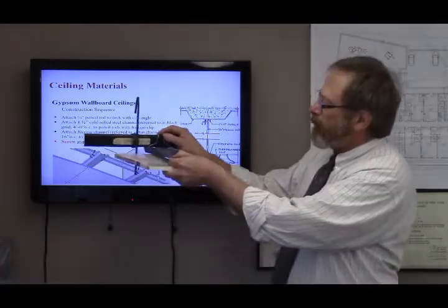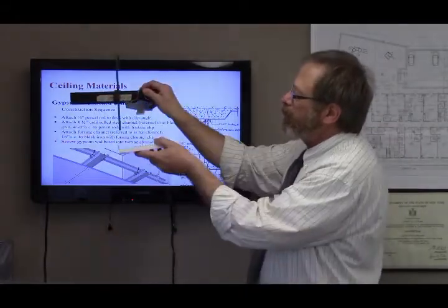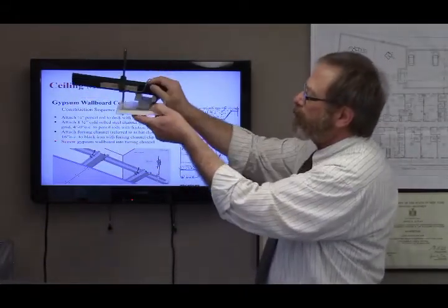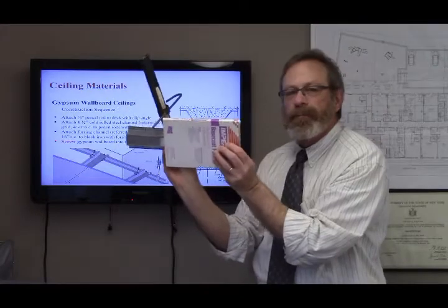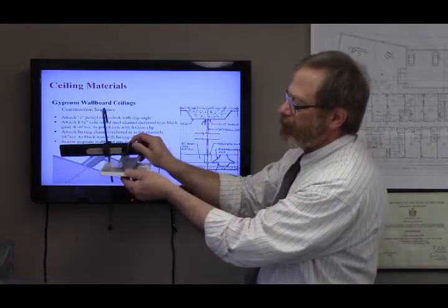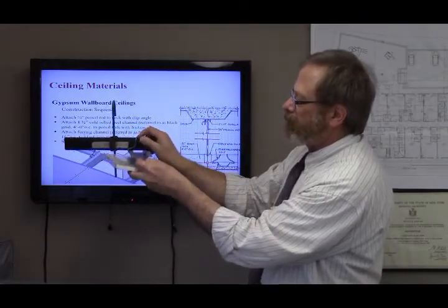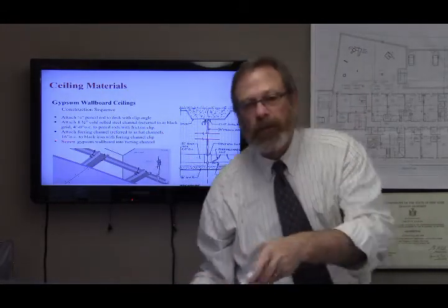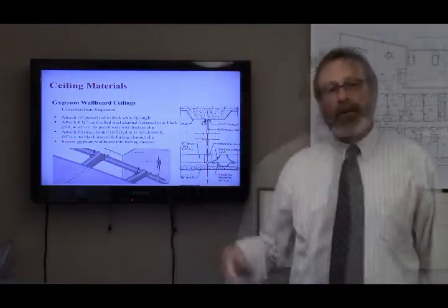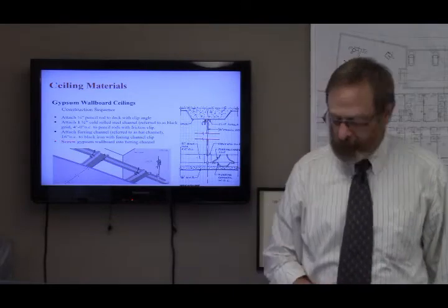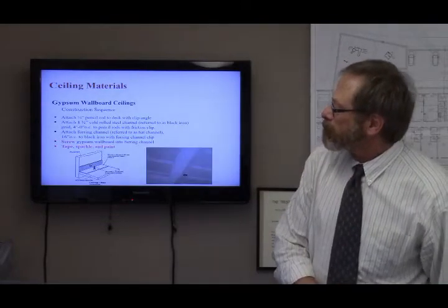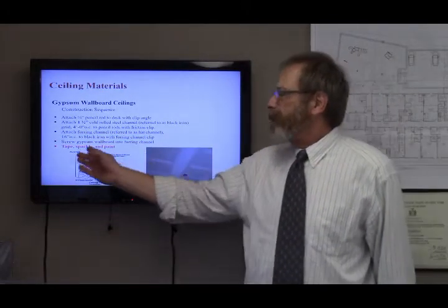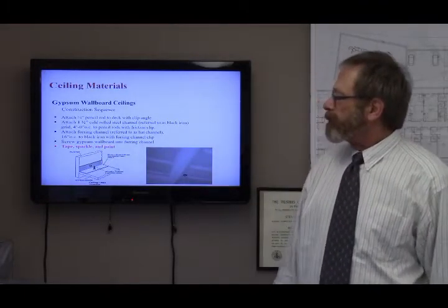And now, once we have that all assembled, we are simply going to take our gypsum wallboard and screw it into those upside down hat channels. And then we finish it off as we would with a rock wall or partition. Meaning tape, spackle, ready for paint.